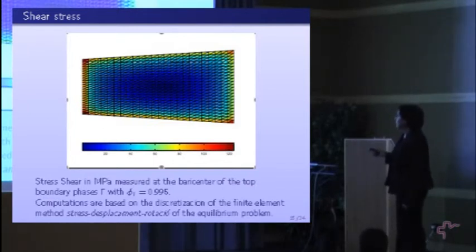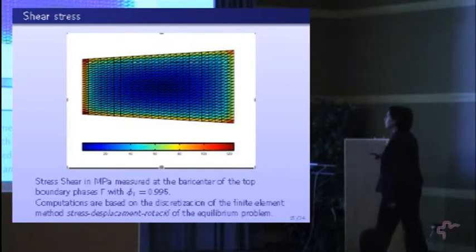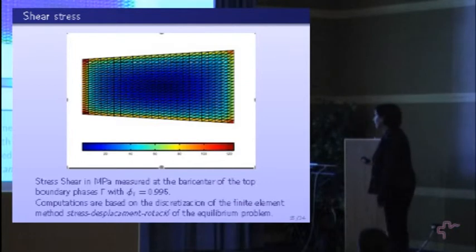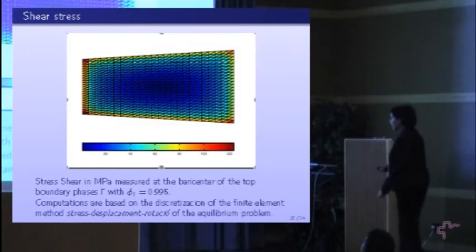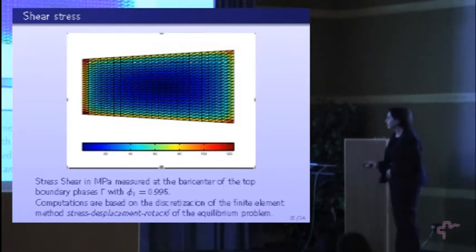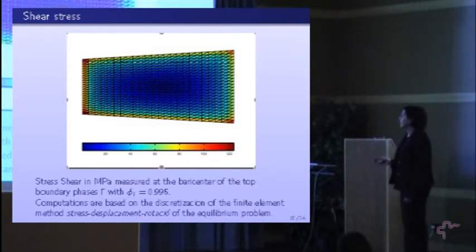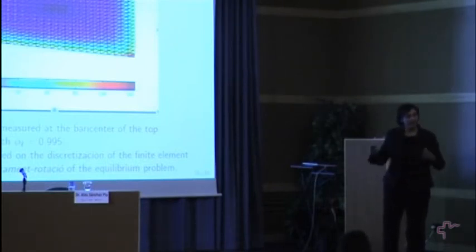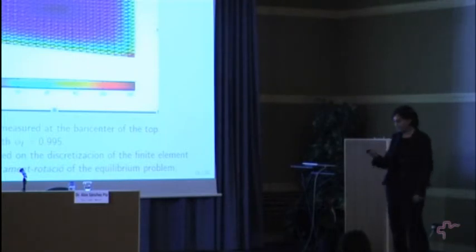And the red means concentrations of stress. So the kind of question that we were asking is how big are these concentrations of stress according to the properties of the polymer, according to the properties of the system. And those are measured in pascals. Let's see, and here I could give a whole talk on the type of finite element method to discretize this. Now, one issue that makes the analysis, and in this case the computations, hard is the fact that this implant has residual stress.